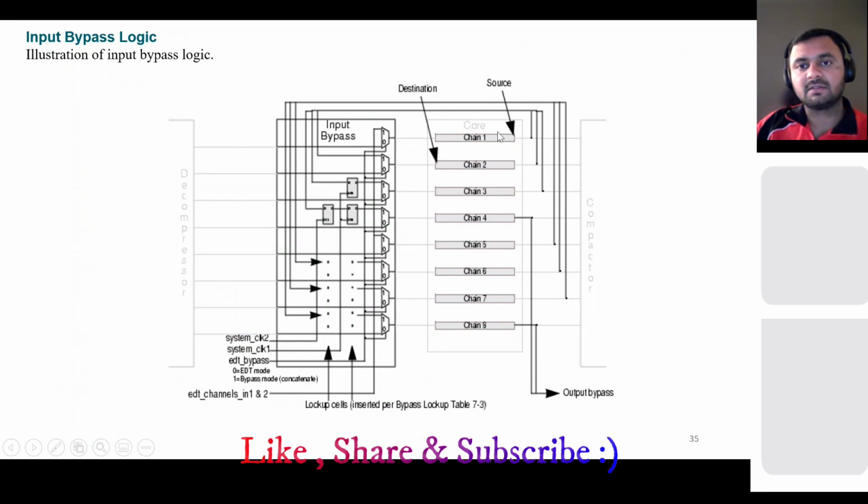Basically you are generating a long chain by using these short chain outputs. You can see here the bypass output is combining all these 8, or at least 4. You have a multiplexer here, where one input will be chains 1 to 4 and the other input will be 5 to 8. You are just making longer chains to debug it.